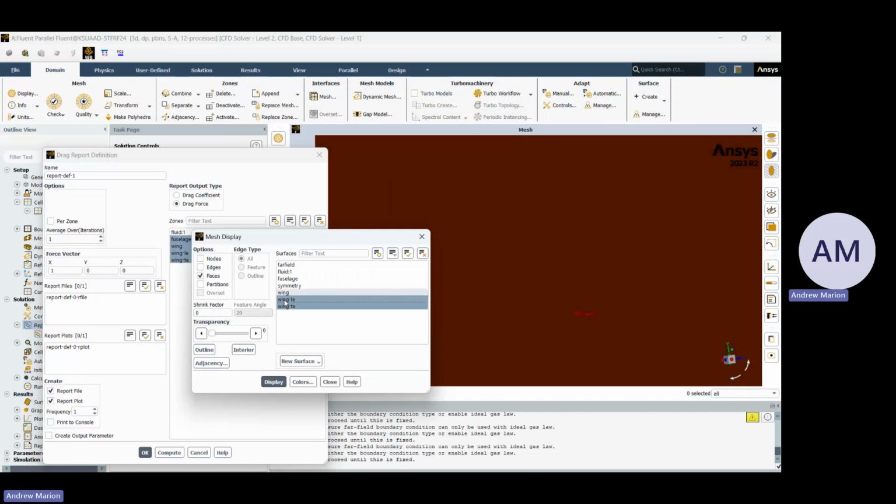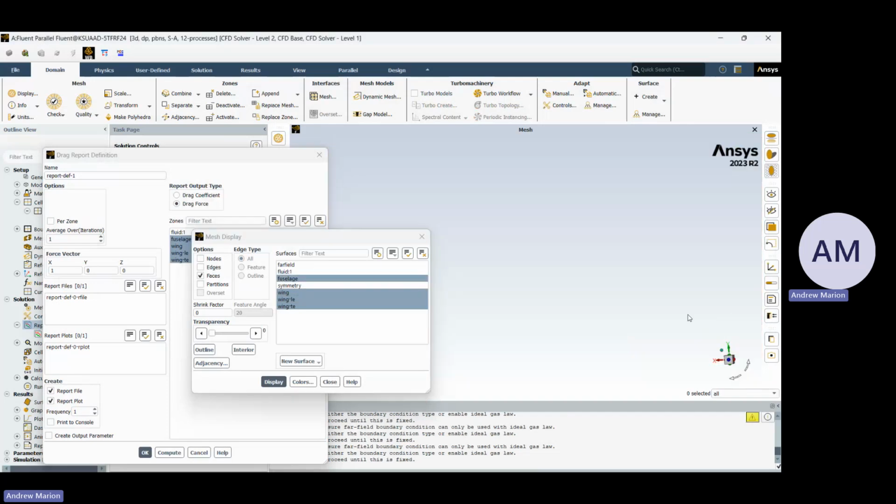It's also a really hard area to compute physically, because almost all of the front-facing edges of aircraft are rounded or sharp in some way. If you're looking at it head on, take a snapshot and calculate the area of what you can see straight on, that's the area the drag equation will use. You could do this in SolidWorks pretty easily. If you had the sketch like this, you would just draw a line that follows the curves that you can see. So it's the area perpendicular to the air, because that's what influences drag.